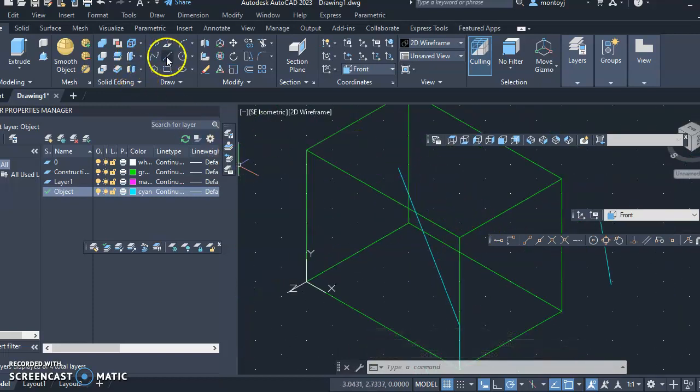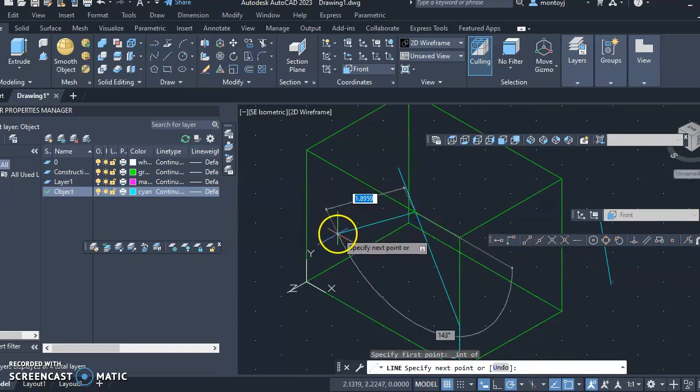So now I'm going to put a line from that intersection, and I'm going to use my snap to be sure that I can grab it. Then the next dimension that we're looking for is something that's in the book, right? And you might miss it because it's on number 12, and then off to the left I put a little arrow to show it. So here's the next point. It's going to be a 30 degree angle, and we're going to use this number 1.7321, and let's see if we got it. And then it's going to say 30 degree increment.